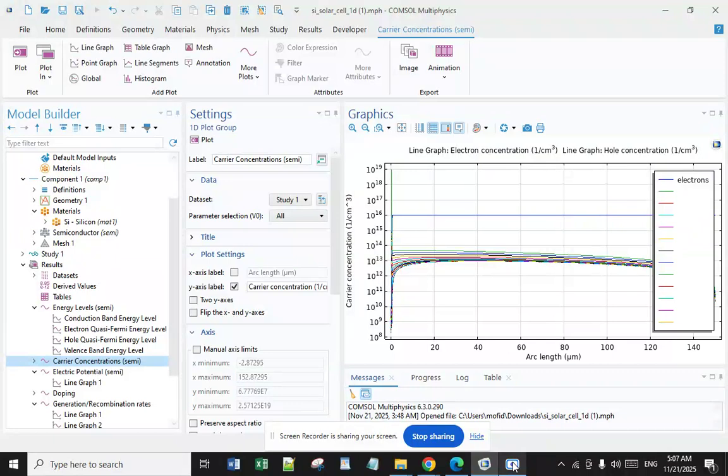When the two materials are joined, electrons diffuse from the n-side to the p-side, and holes diffuse from the p-side to the n-side. This leaves behind fixed positive ions on the n-side and negative ions on the p-side, creating a region depleted of free charge carriers known as the depletion region. And the next part is the electric field. The fixed positive and negative ions in the depletion region create an internal electric field that opposes further diffusion, establishing an equilibrium. And what about the applications?